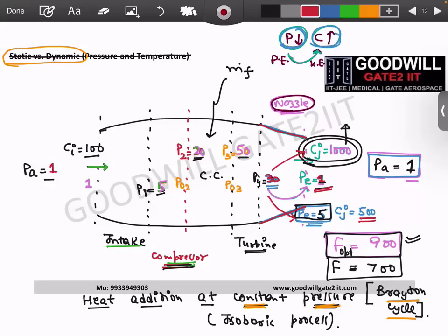Okay. So Shlok asked this question. Sir, then is it the case that in the optimum case, fuel is consumed completely? So keep one thing in mind. Fuel is in your hand. If you want it to burn 2 kg, you will be burning 2 kg. Keep this in mind. This is kg per second, right? Till the time you keep on burning and sending it, you will be producing thrust. So thrust has nothing to do with whether complete fuel is burnt or not.